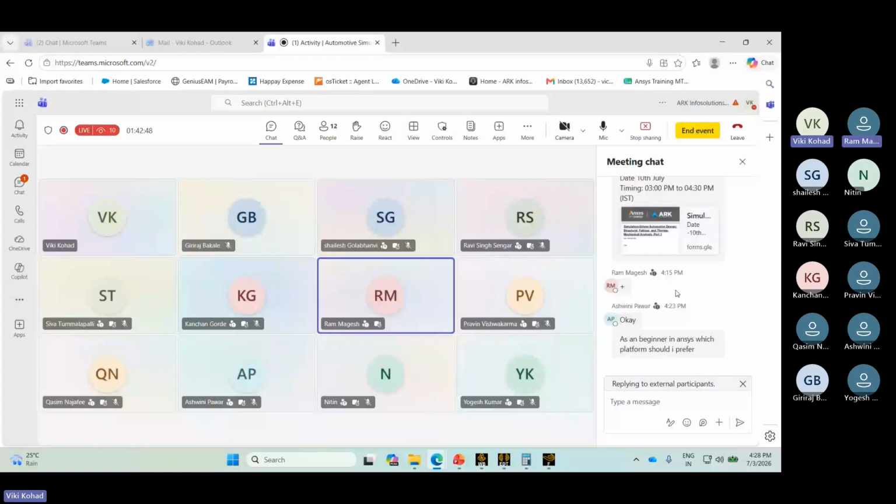Yes, you have to add the materials in the library. But for that, you first need the properties of that material. If the material you want to use is not available in the library, you should know the properties, like how much the permeability is. If it is a magnet, how much the coercivity value is. Then you can create the material.